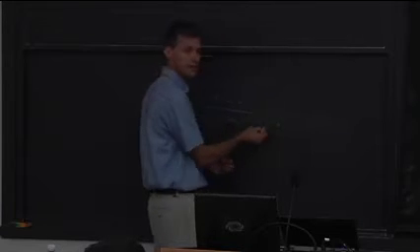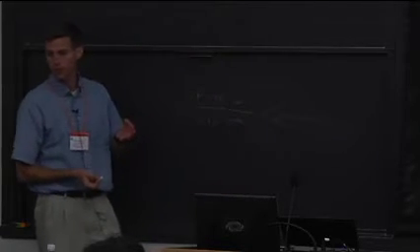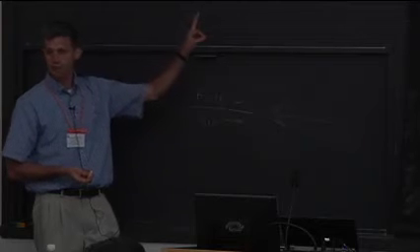Oh, I'm offset here. This shouldn't look like that. The flow is actually decelerating ahead of the flame like this because of the gas expansion. And so the flame can actually sit in a spot where the flow velocity is higher than the flame speed, for the exact same reason.